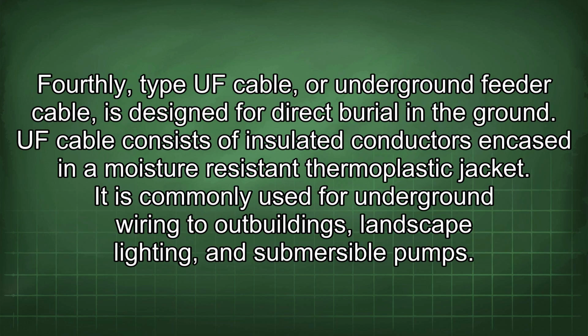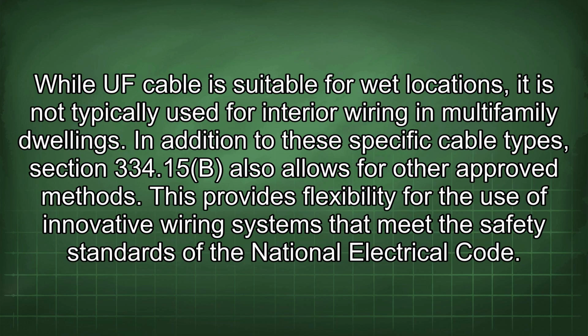Fourthly, type UF cable, or underground feeder cable, is designed for direct burial in the ground. UF cable consists of insulated conductors encased in a moisture-resistant thermoplastic jacket. It is commonly used for underground wiring to outbuildings, landscape lighting, and submersible pumps. While UF cable is suitable for wet locations, it is not typically used for interior wiring in multifamily dwellings.